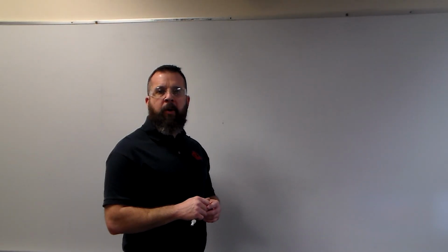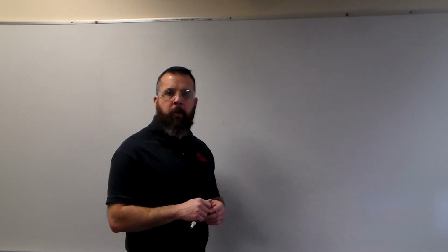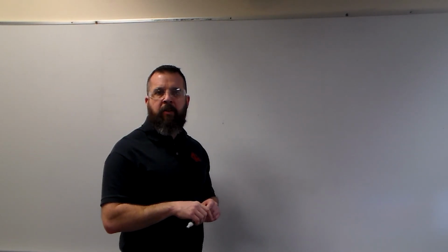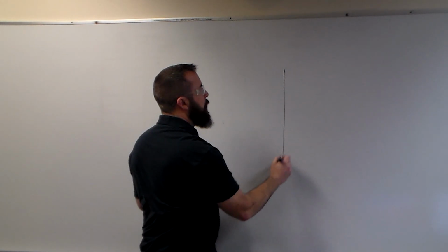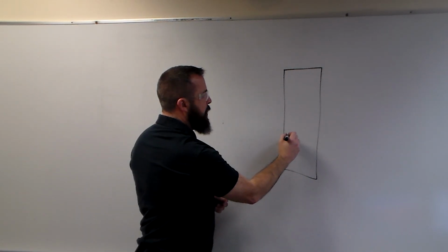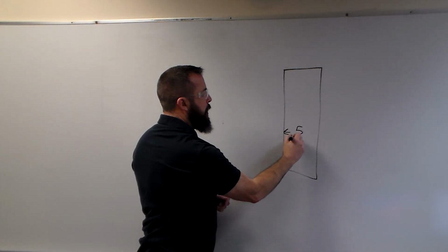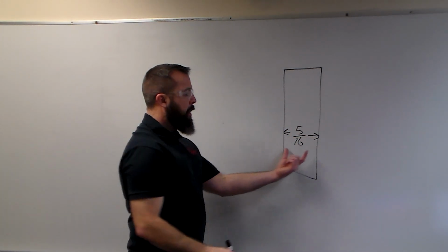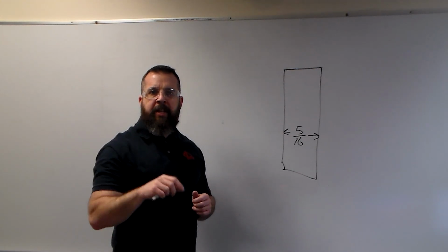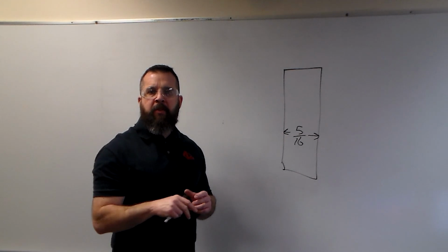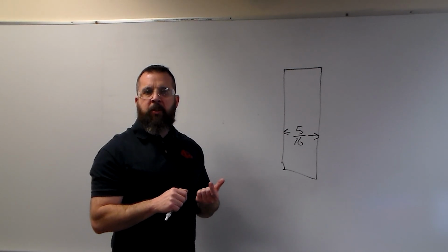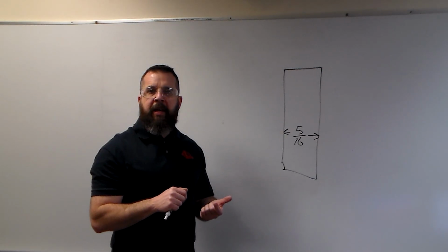This quick video is going to go over how to grind your thread relief grooving tool. So you're going to get a piece of 5/16 inch wide high-speed steel tooling. That's what that represents there. And that's the 5/16. Now, you'll notice on your print that you make a groove that's 3/16 of an inch wide, and then you make some grooves that are 1/8 inch wide.